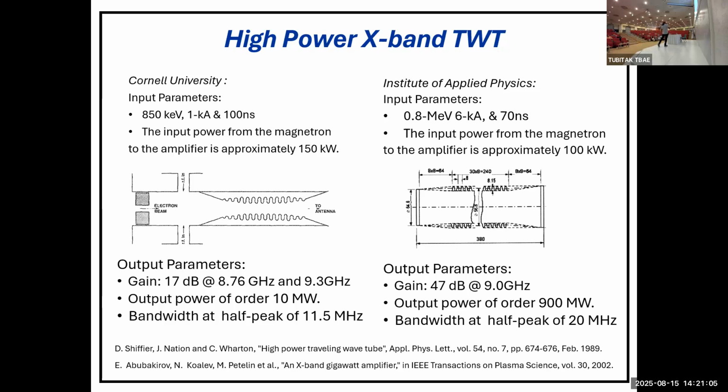Again, once you inject your signal, there is no reason that the signal will follow the path you are hoping for, toward the output, and amplify. Some of the power will go toward the cathode unless you do something about it. You're going to add some reflection here, right? But this reflection is not going to be in the interaction region. It's not going to contribute to oscillation, just like for the input, seed signal.